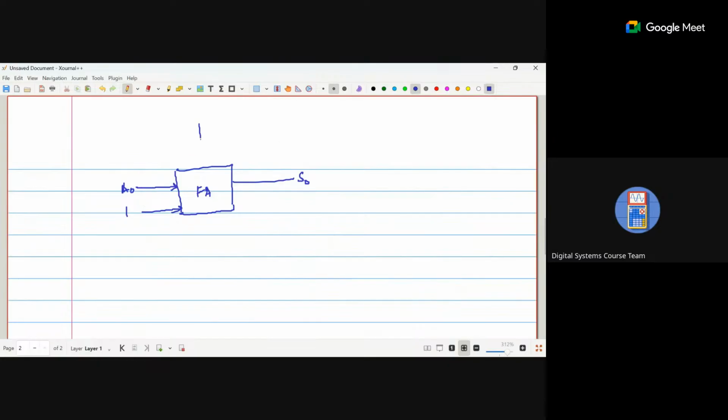So for that, we will add a flip flop here, which has a clock, and this will be considered as the input, and the output here will go as the input for this particular adder. This will be Q. So this clock will control the frequency. Not every output goes here, only the output you prefer depending on the frequency you have given. And that's how you will control your counter here.